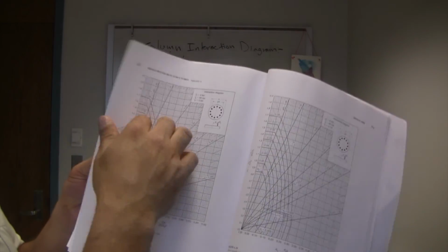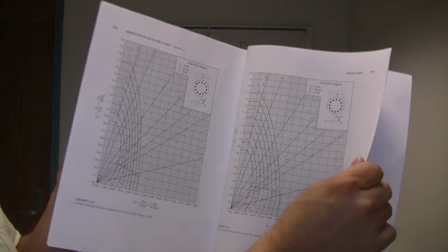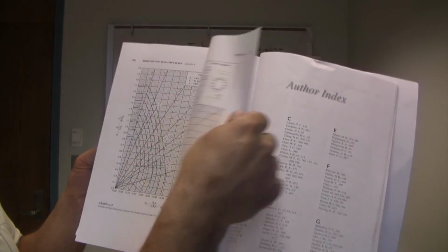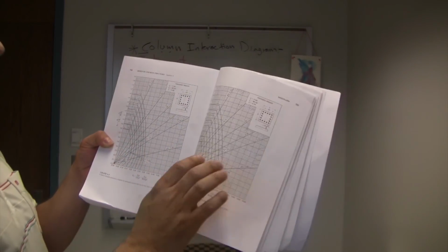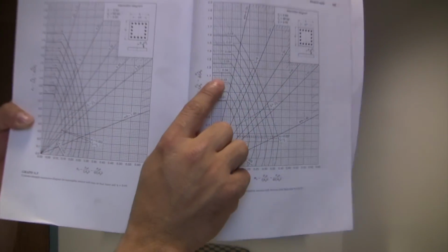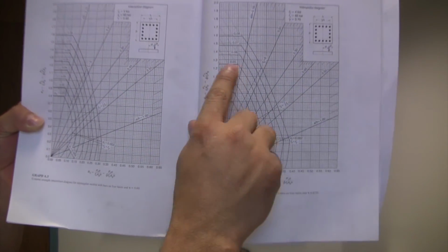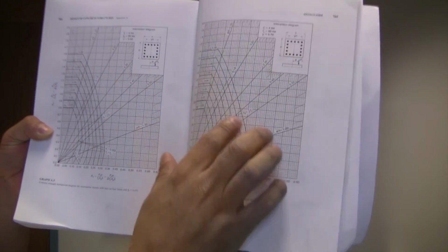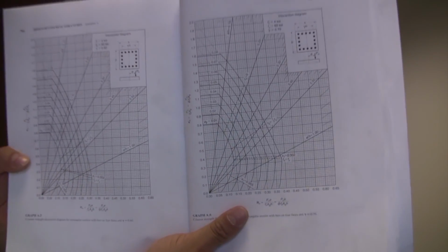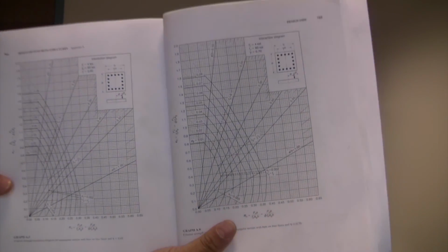Then you start with the circular column, and it's the same case, just gamma. Okay, so these are the interaction diagrams, and this is the cut I told you about here. Once you reach here, you see these horizontal cuts, which account for accidental eccentricity. So when you design a column using the interaction diagrams or the equations that I covered in the previous lecture, that accounts for small eccentricity.